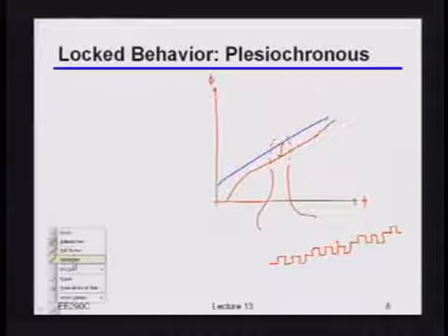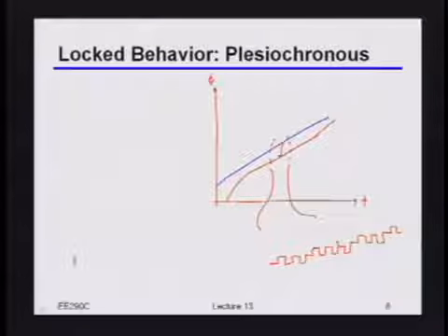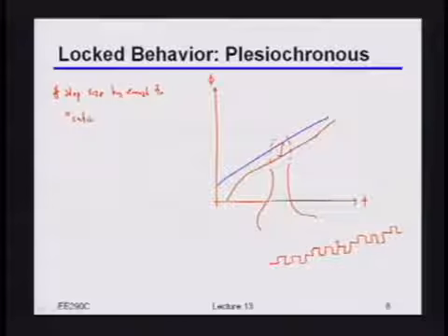We said before that we want to make those step sizes really small, right? But what's the zero-order constraint that you have to satisfy if you're going to make this thing actually work, given there's some reasonable ppm offset between them? That it can catch up as fast as the ramp. Yeah, exactly. So here you have to make sure that your step size is big enough to basically, as you said, quote-unquote, catch the ramp.